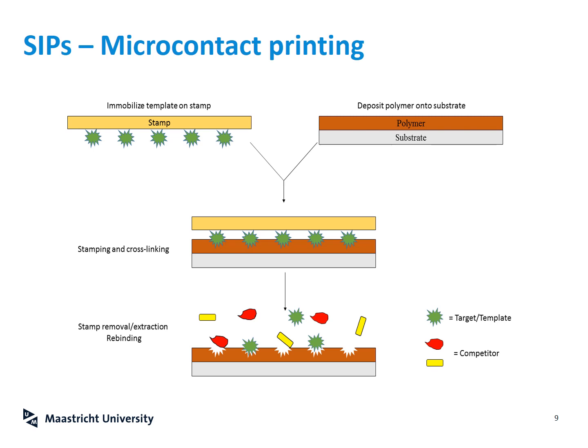It's a very simple approach in which you just take your monomers, your cross-linker and your initiator, you dissolve them, and you let them pre-polymerize. And when they become jelly, you spin coat them onto a substrate, where you basically just spin the substrate, put a drop of polymer onto it, and a nice flat layer will be deposited onto your substrate. Now, this polymer is not fully polymerized yet, so it's still soft enough to be deformed, but hard enough to